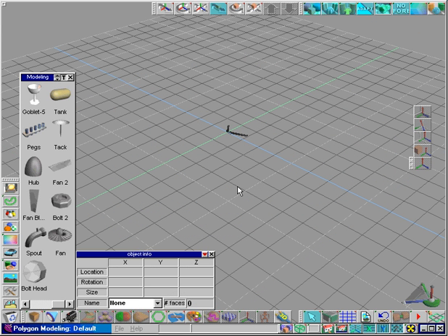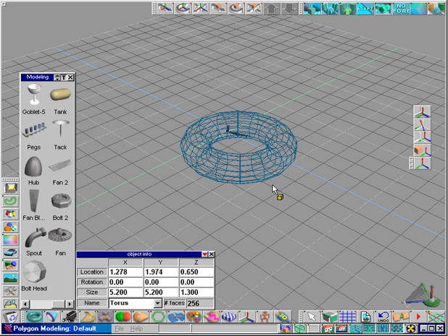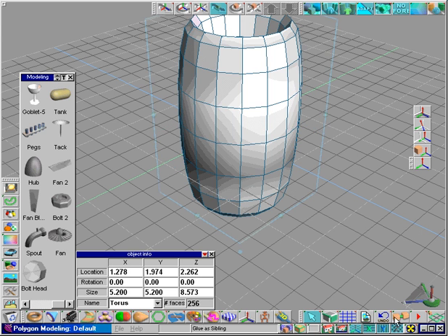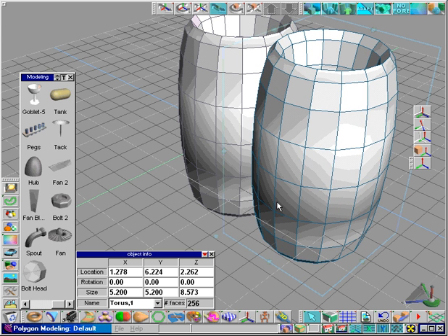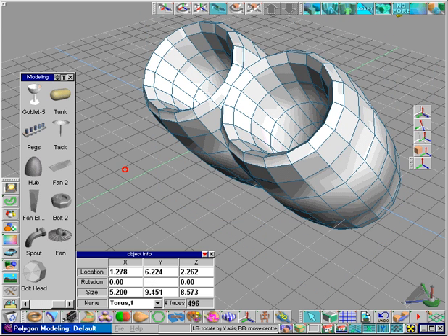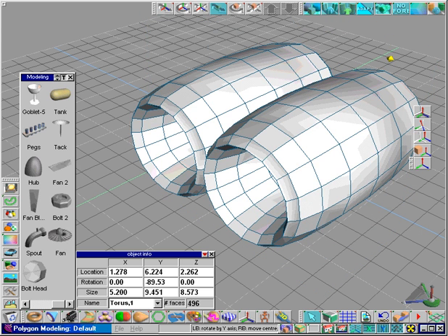The last tool is the Normalize Scale tool. This will return geometry to its native size and scale under certain conditions. The basic operating principles are as follows. Create a torus and scale it in Z. Copy the torus, move it over, and Boolean it to the first. Rotate it about 90 degrees in Y. Now click on the Normalize Scale tool.